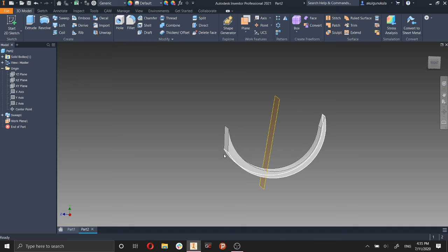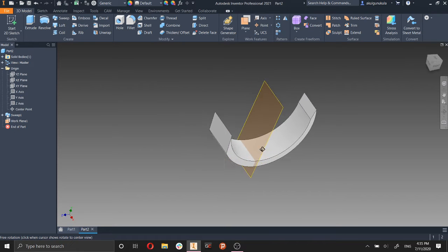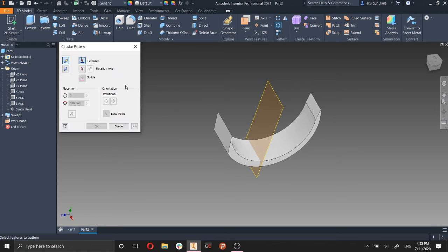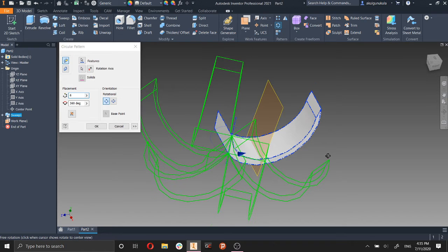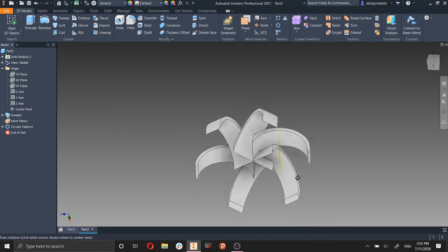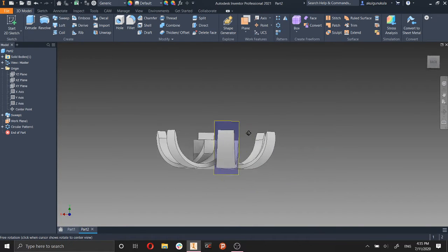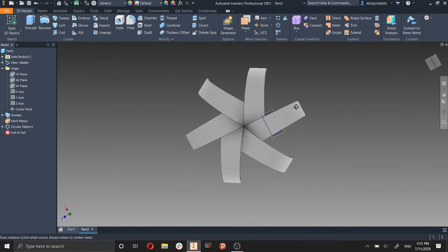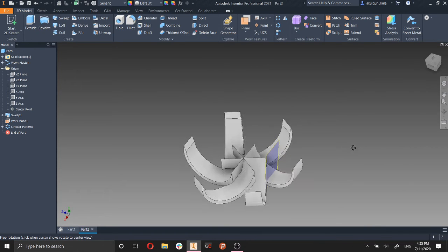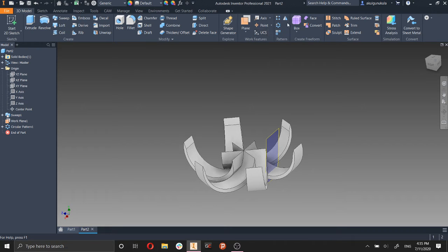You can do it as you like. You can do an axis and then just revolve it around that. Let me just show that. So I'll choose this feature and rotation axis. Why not? And it looks interesting. Yeah, that looks pretty cool. But yeah, it's just cool in CAD. I don't think you can really recreate this in real life. Maybe, maybe not. I'm not going to delve into the actual things of it. But yeah, those are the pattern tools: rectangular pattern, mirror, and circular pattern.